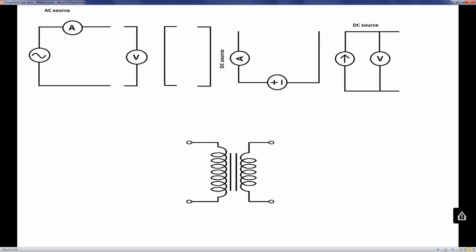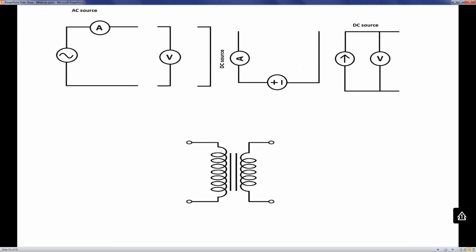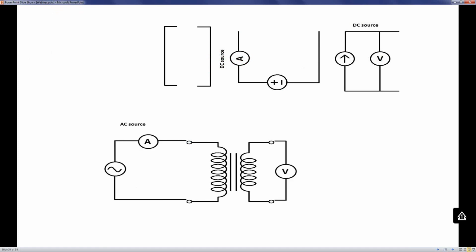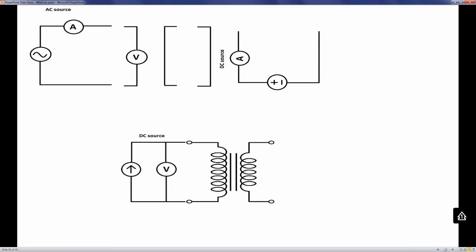So this is what it would look like if I were to represent everything in a simplistic format. This is what the sequence would look like. I would start off with the sweep frequency response analysis, get done with that. Then I move on to the turns ratio test. This is the circuit for the turns ratio test. Once I'm done, I switch over from the TTR test set to the MTO test set, and I do the winding resistance test. Then I move on to the insulation tests.